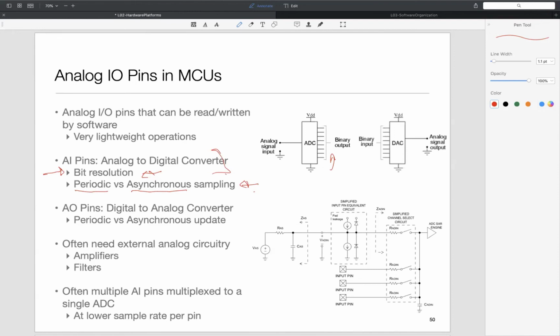That's true, but it's a sufficient condition. It's not a necessary condition. So in the past 15 or 20 years or so, a whole field has emerged which has been looking at smarter ways of sampling. And intuitively, if you think about it, we sample, let's say, a speech signal, but after that we are able to compress it. So clearly, I was sampling redundantly, right? If we sample it using the Nyquist rate, using a 2f formula, but then we compress it, then if it was truly the minimum sample rate that was needed, I should not be able to compress it, right?